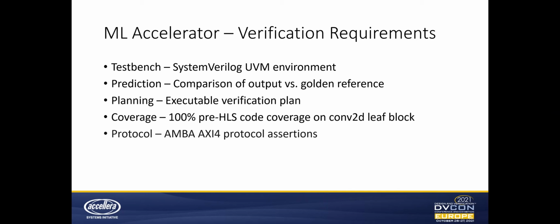The test plan also requires us to close on functional coverage goals specific to this design, such as different configuration setups and input data. Questa VIP components were used to drive AXI activity and to monitor the interfaces for protocol adherence, and to measure bus utilization.